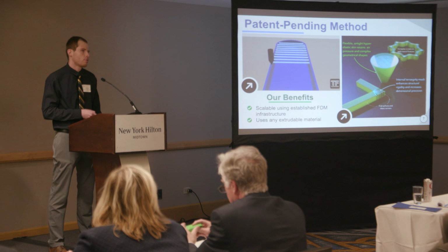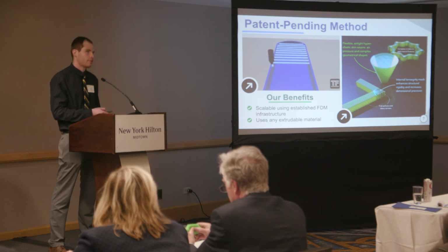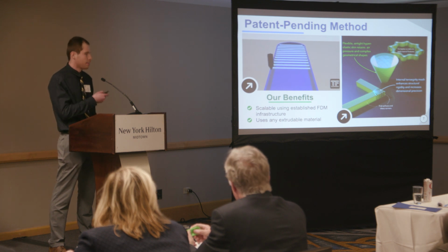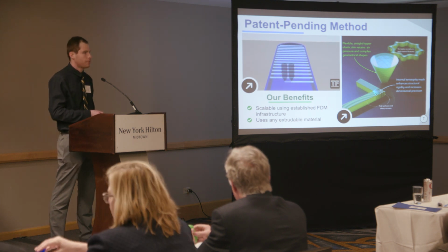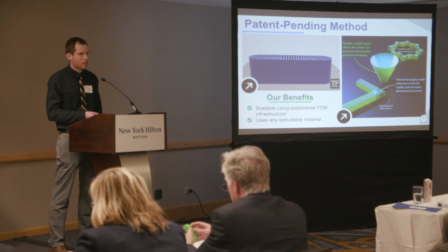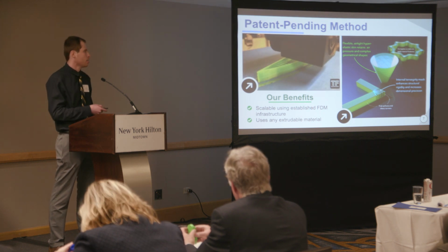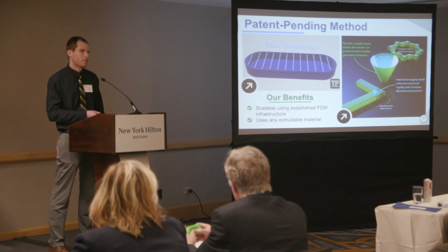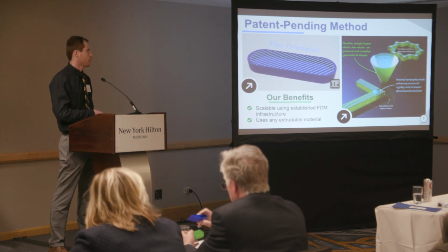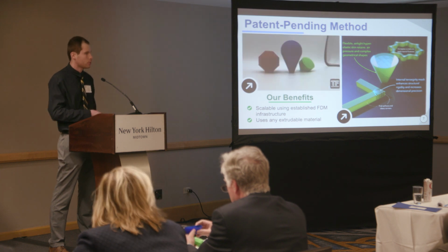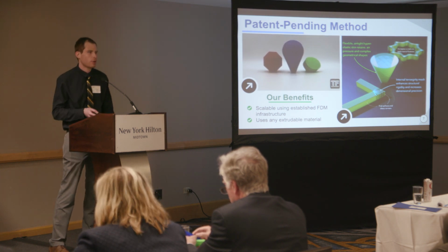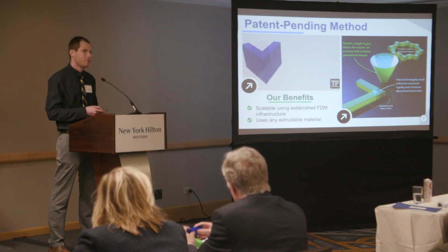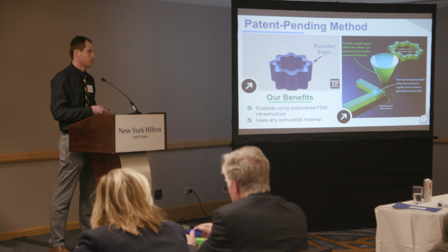The secret behind our process is our innovative, patent-pending manufacturing process. We use 3D printing to customize nearly every aspect of the TenseFlatable structure. We can change how the fibrous tensegrity mesh on the inside is oriented, the fiber thickness, the fiber density, and the fiber orientation, and all of this helps to keep the inflatable shape. Because of this, we can produce many different types of inflatable structures, like those with complex curves and external or internal features. But most importantly, TenseFlatables can create flat surfaces and sharp corners that you would not be able to see in current inflatable techniques.